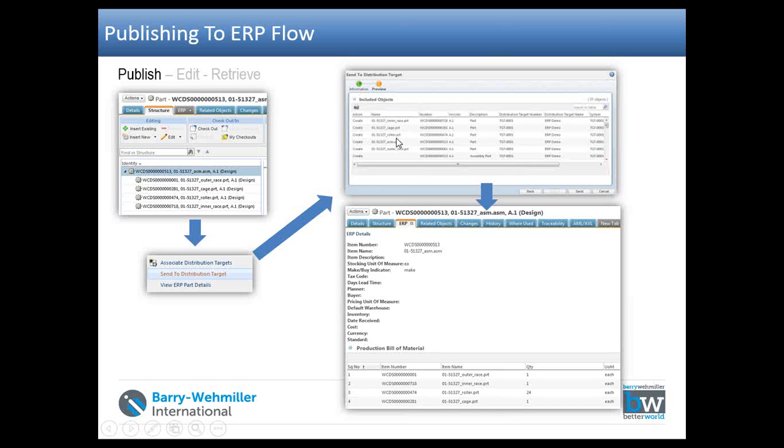of the bill of material is shown, whether it is a create, you can see here in the leftmost column the actions. If it is new to the ERP, the part number, then it will show as a create. If it is a change, it is the second time, after revising and making some modifications, if it is going a second time or later, then it will come as a change, or in some cases delete. These actions are available in this list, and then you can go for the finish.